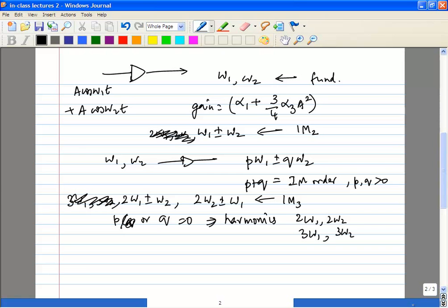And the second stage is also nonlinear, so the second order intermodulation between 2 omega 1 and omega 2 could give you a 2 omega 1 minus omega 2 component, but that will happen only if you have a cascade of stages. In a single stage represented by a cubic nonlinearity, it comes from the cubed term, not necessarily from any inherent squaring.